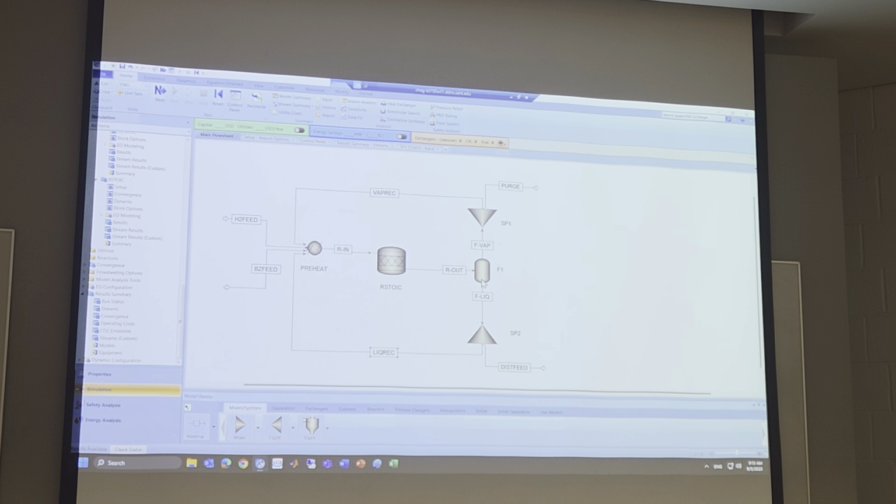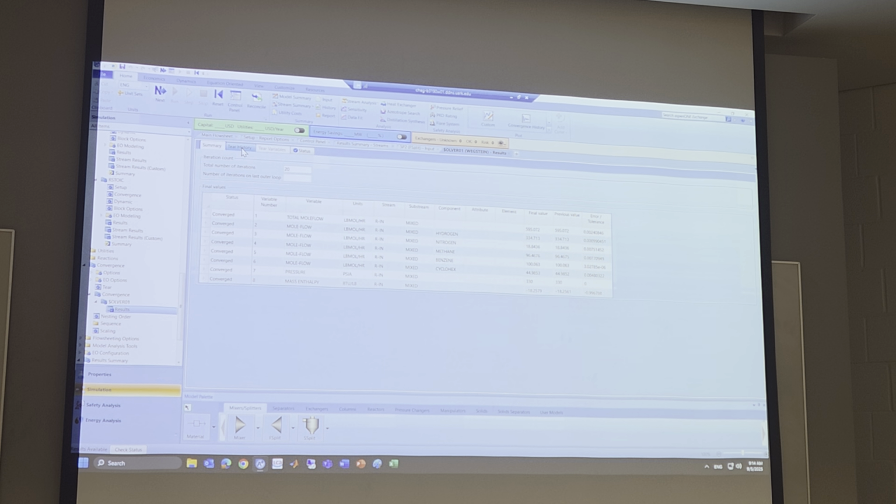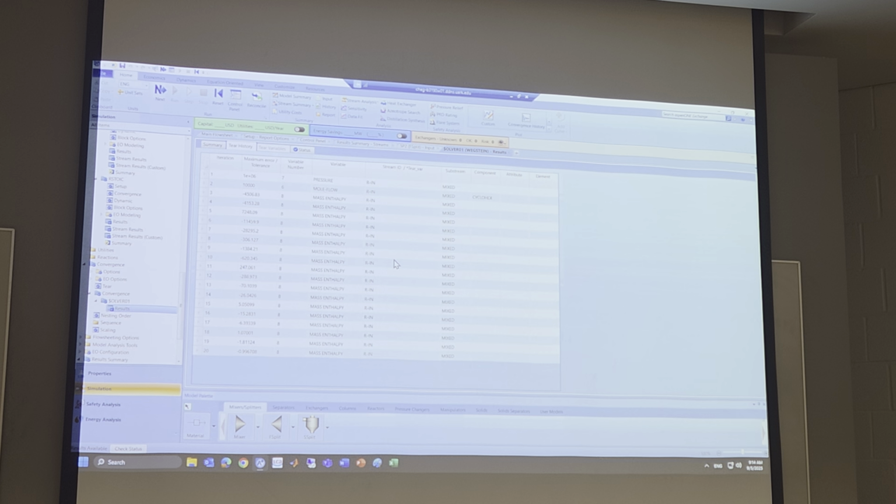Okay? One-time calculation, second-time iterative calculation. It's called SM calculation, sequential modular iterative calculation. Now, if you go to the Convergence folder in the navigation pane, you can check convergence and get better information. If you go to Results, here History, then how does Aspen do this iterative sequential modular calculation?